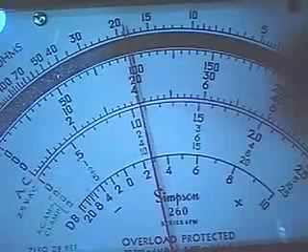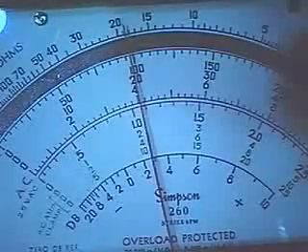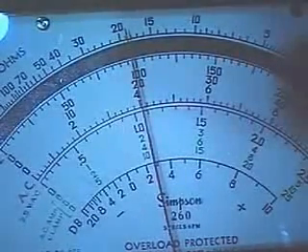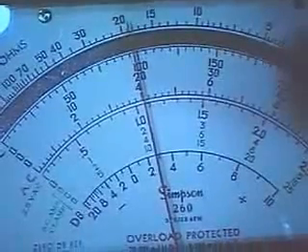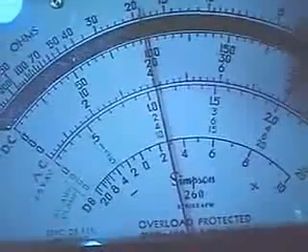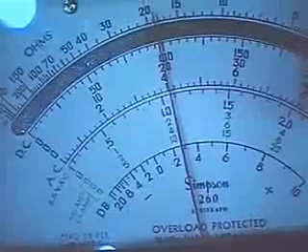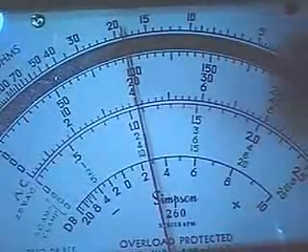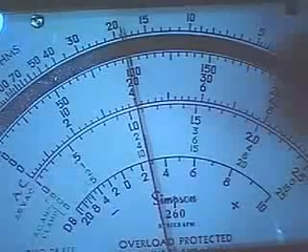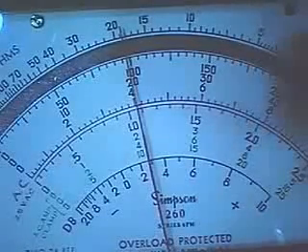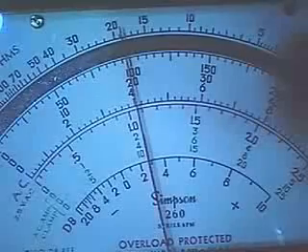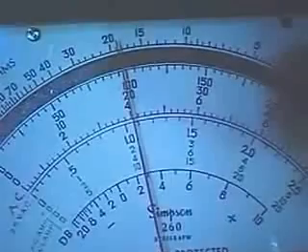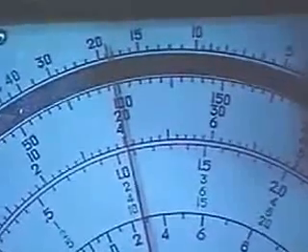So what I'm going to do now is increase the frequency. As I increase the frequency driving the inverter, what should happen to this needle? The waveform should become closer and closer together, and the needle should begin to go up. As I increase the frequency, it should consume more and more power, and the needle should start going up. So let me do that for you. In terms of numbers, it's on top of the 4 on the scale in the middle. I'm going to increase the frequency very slowly.